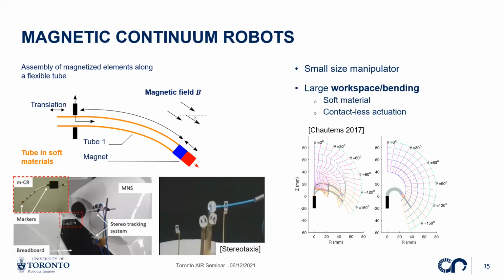But now the researchers working on these magnetic continuum robots try to increase the number of degrees of freedom by having either a serial robot arm that carries magnets and can be closer to the robot and create more different magnetic fields, or by iterating on this design of magnetic navigation system. So you're right, it's challenging. Currently, in the state of the art, it's mostly homogeneous magnetic fields, but it's evolving towards multi-magnet robots and control. Okay.